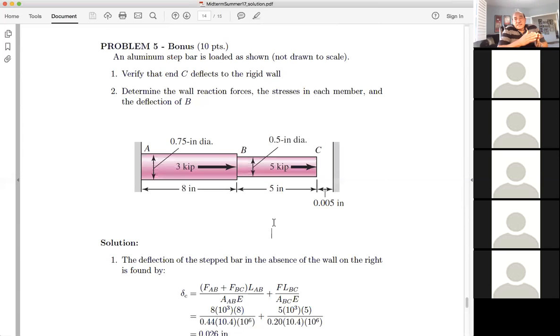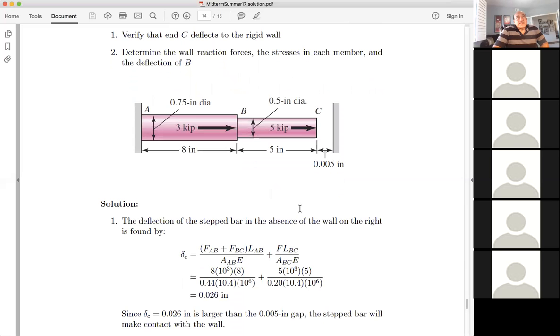So you can calculate the expansion in the tube, and if the walls are rigid, you can also set up the forces from the wall, and then the constraint would be the size of the gap, which is given, and therefore you can calculate thermal stresses in that case. So you can see variations on this. There could be thermal stresses, or additional forces on it, but one has to think about the ideas of equilibrium in every section in there.